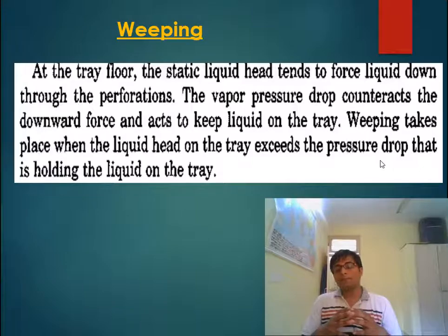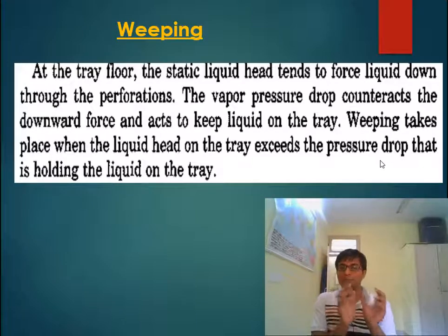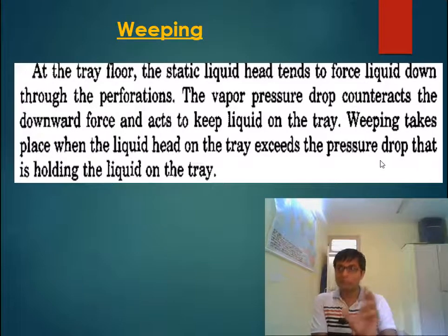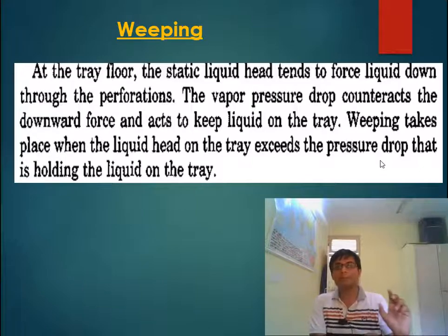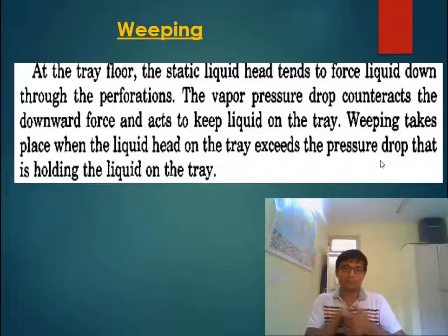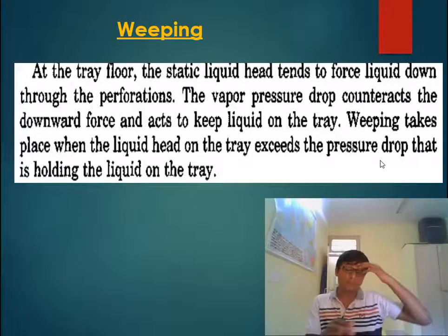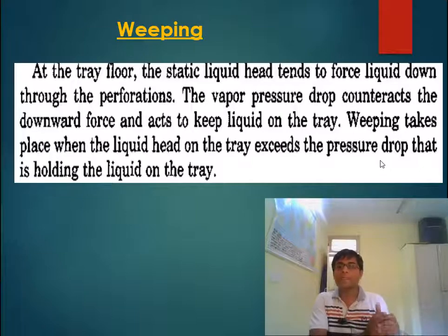I found that they have written that weeping will take place when X becomes less than Y. I mean, when dry tray pressure drop becomes less than hydraulic tray pressure drop. So that was not clear, through the tray hydraulics or through the pressure profile.